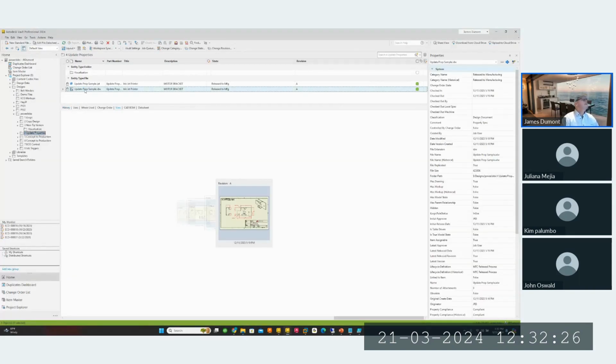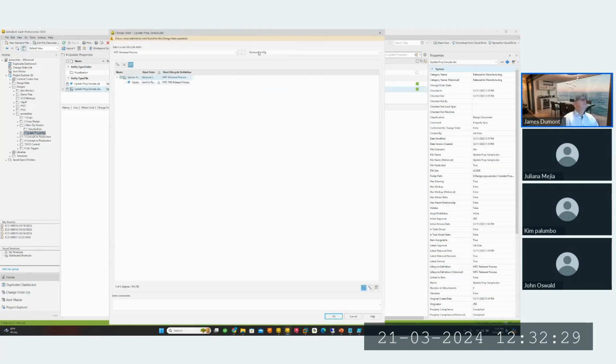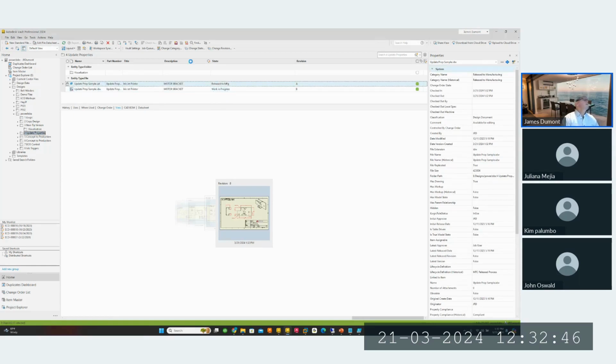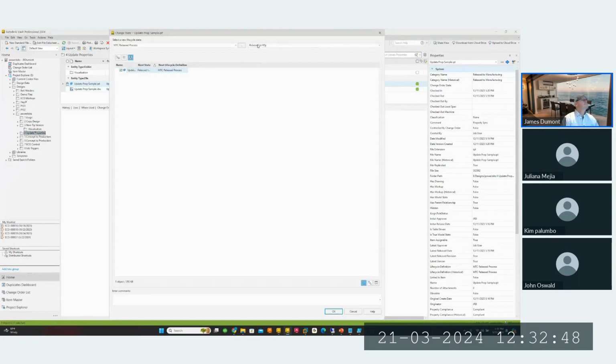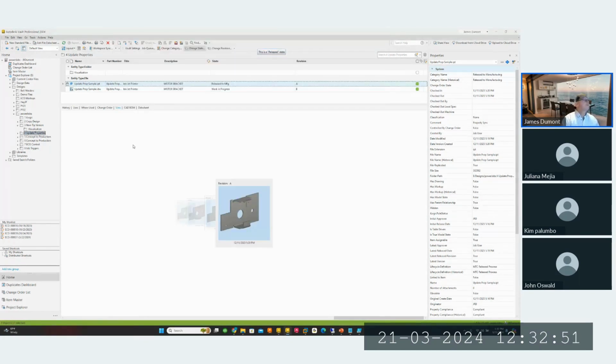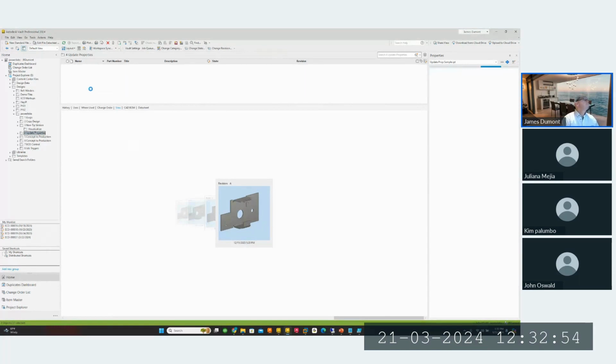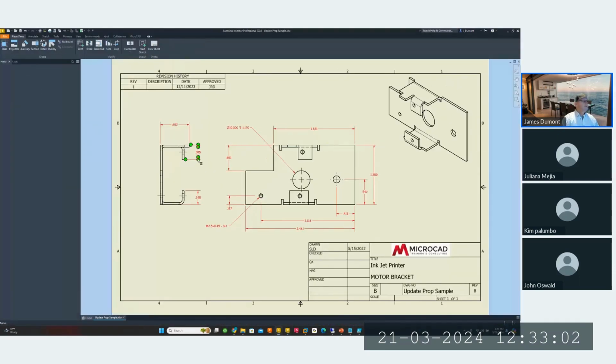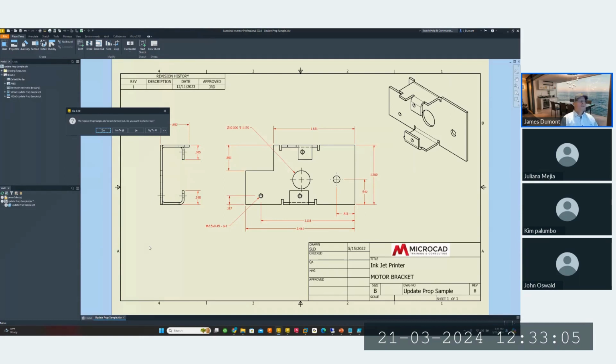And all I have to do here is take this file, I change the state from released to WIP, and it's actually processing it right now. I don't have to wait the 1 to 10 minutes. It's immediate because it's an event configuration and it changes it. I've got to do that one too. Not that it matters because it's the properties. So if I open up this file, I'll just open it. I'm not going to check it out. It clears all of those settings. And all I had to do is change the state.